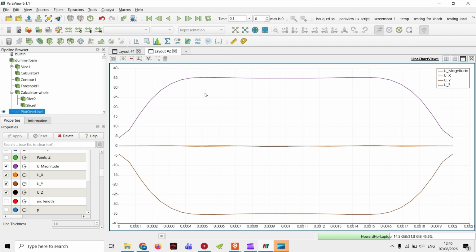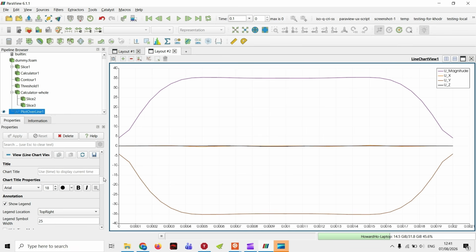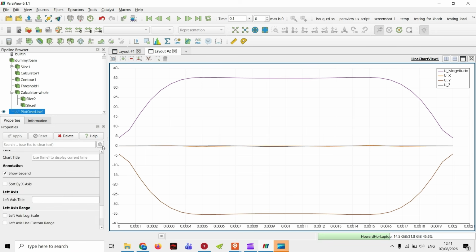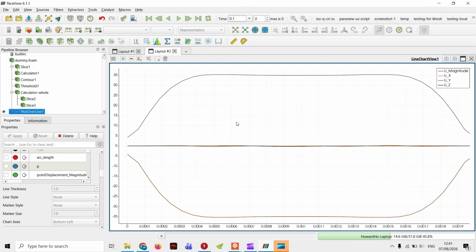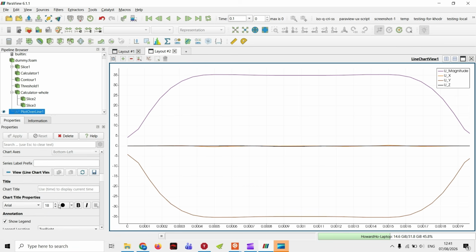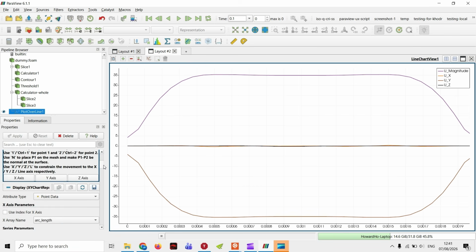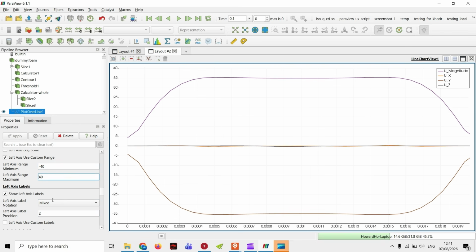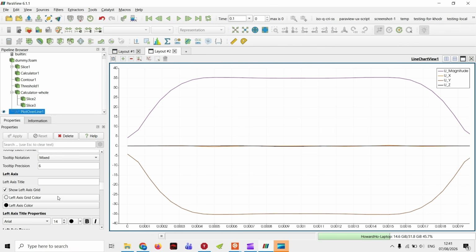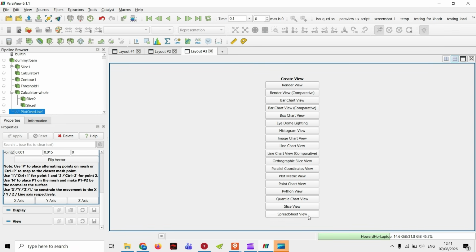Now, the line plot feature in ParaView, in my opinion, is okay for just quickly visualizing your data. It's quite limiting. You can adjust the axes, but to do that, you have to scroll in and out and drag yourself around in the view. Then it unlocks the axes option, right here. So it allows you to adjust the minimum and maximum. You can realign it. But what I tend to like is just exporting these as CSV to plot in Python or MATLAB.